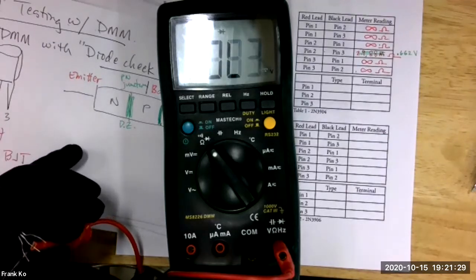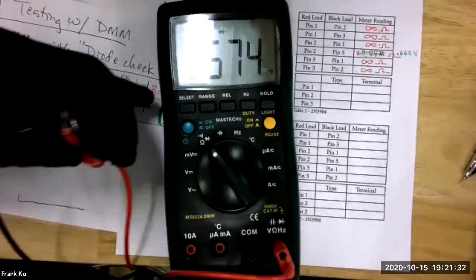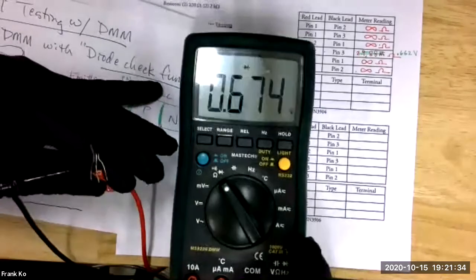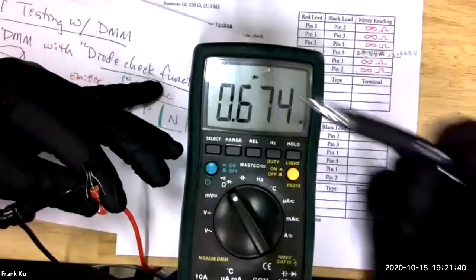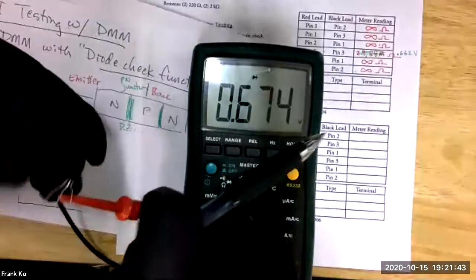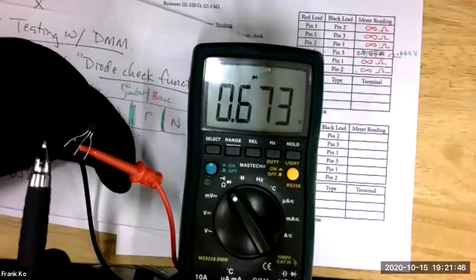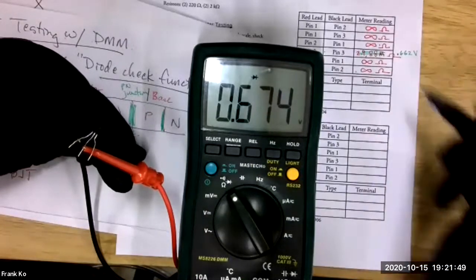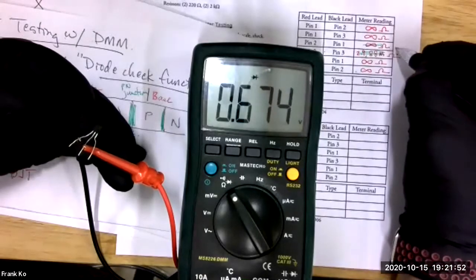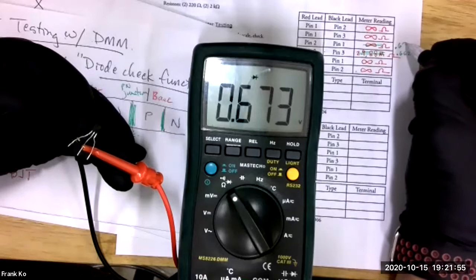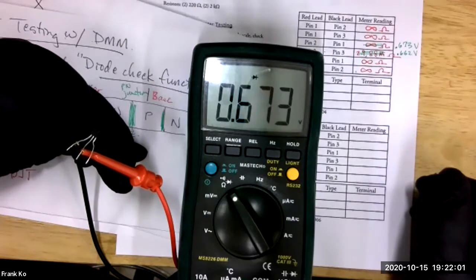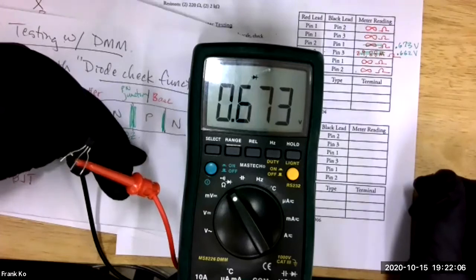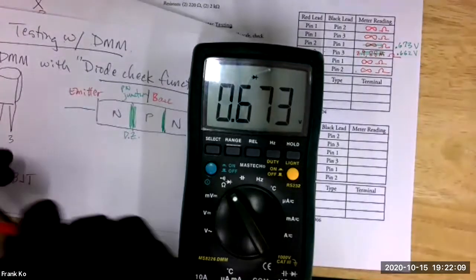And now, to make sure, let's go ahead and do a 2-1 combination. Could you do a 2-1 combination, please? A 2-1 combination using your diode check. Forgive me, I think even on my own, I didn't have the diode check function on. So with the diode check function on, are we red to 2 and black to 1? Okay, and I get 0.673 volts. Okay, and what reading do you get, Chris? Carlos? Okay. All right, record that value because each of your values is going to be slightly different.